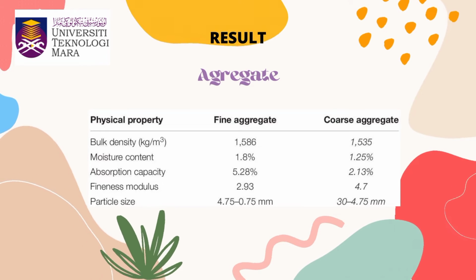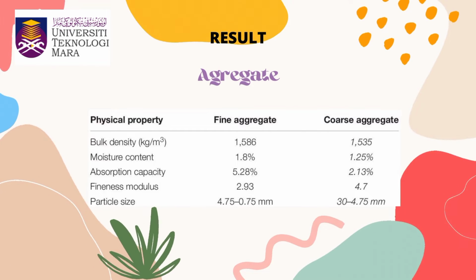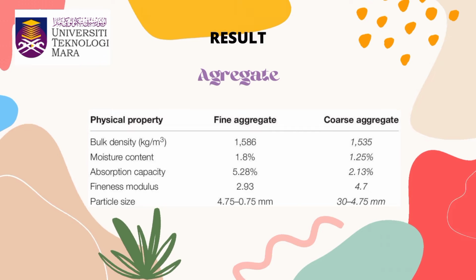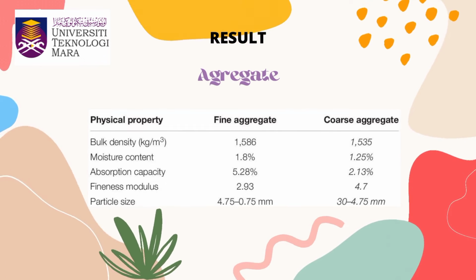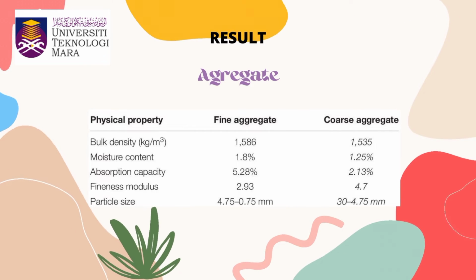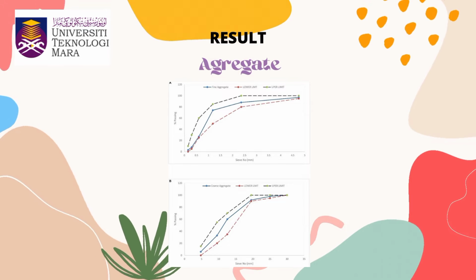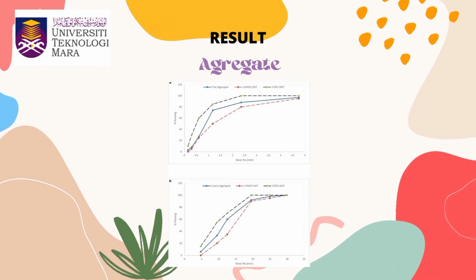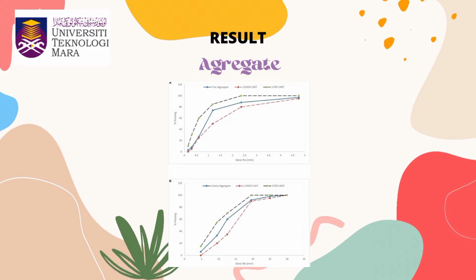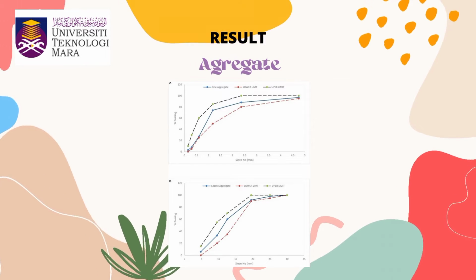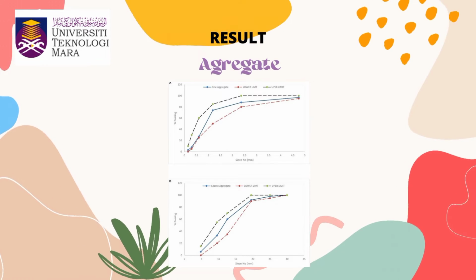Aggregate. For fine aggregates, typical natural sand obtained from Lawrencepur was utilized in saturated surface dry conditions in entire blends. The coarse aggregate used in this study was obtained from Margalla in saturated surface dry condition and was used in all blends. The maximum size of coarse aggregate is 30 mm. Tests were performed to determine aggregate physical parameters.